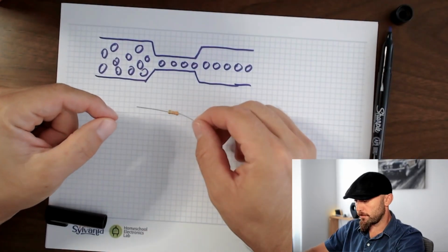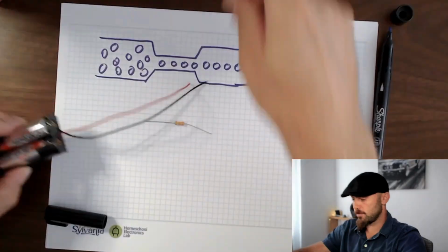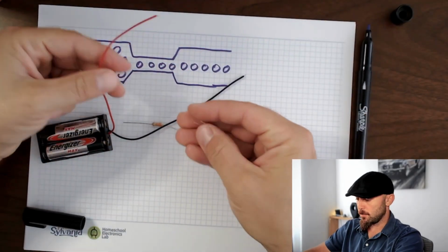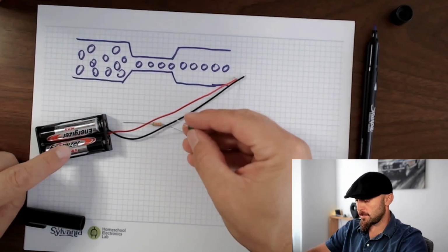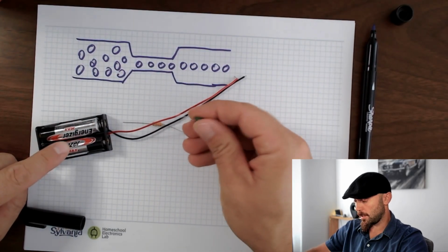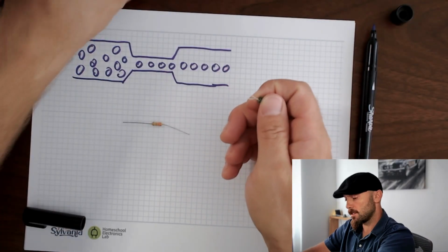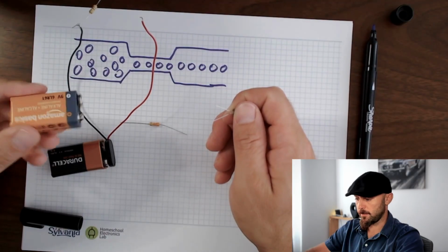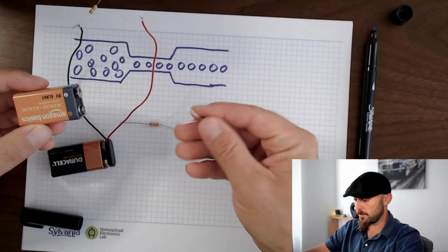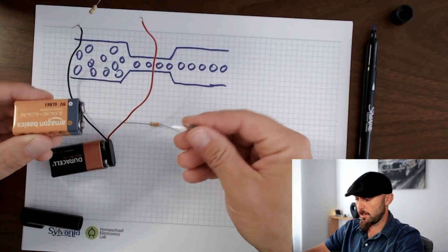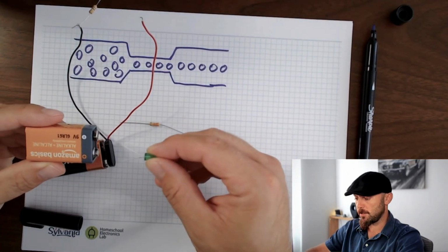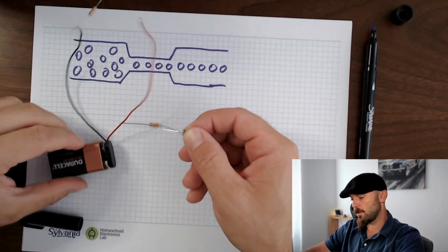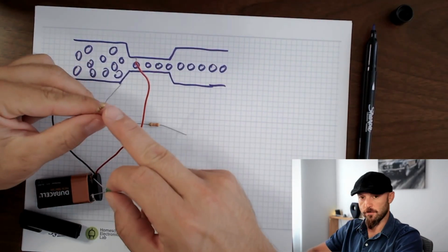This is very important. In previous examples, we talked about this type of battery and this type of LED, which works perfectly because it has the exact amount of voltage that an LED needs. However, in most cases, we'll have a different type of battery. Every component is a little bit different and may need different voltage. If I would connect this LED directly to this battery, it would immediately burn out. So I need to restrict the flow of the current using a resistor.